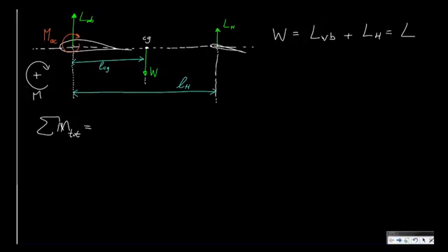It is, first of all, the moment around the aerodynamic center. And because there's equilibrium of forces, we can also place this at the center of gravity. So if we look at the moment around the center of gravity, we can just use the moment around the aerodynamic center as if it was around the center of gravity, because there's an equilibrium of forces in the vertical direction. We can just displace the moment and the number doesn't change.